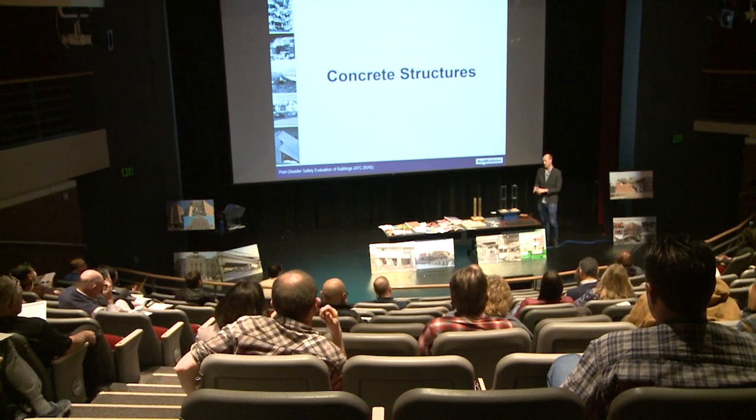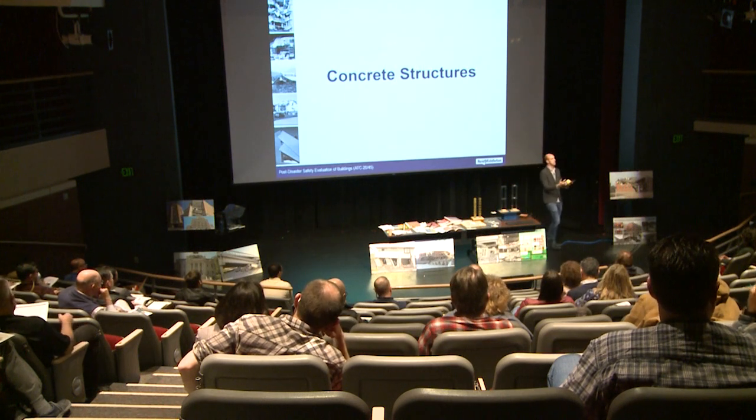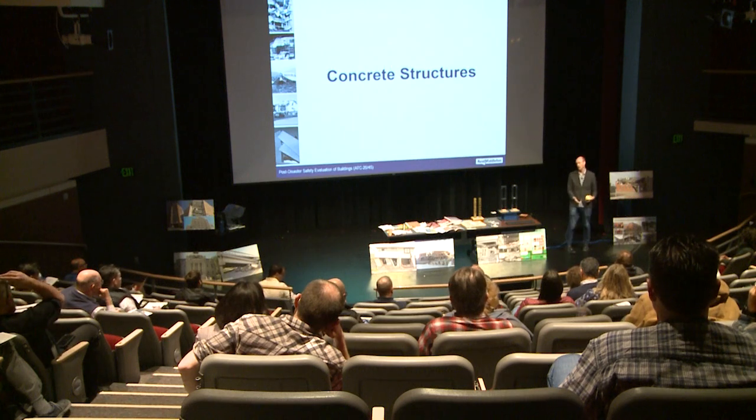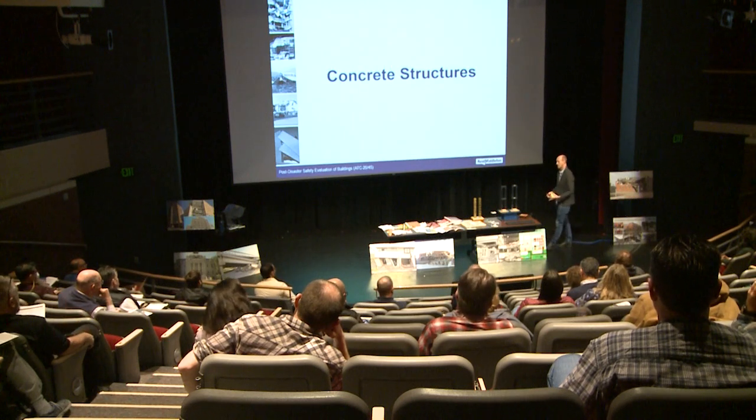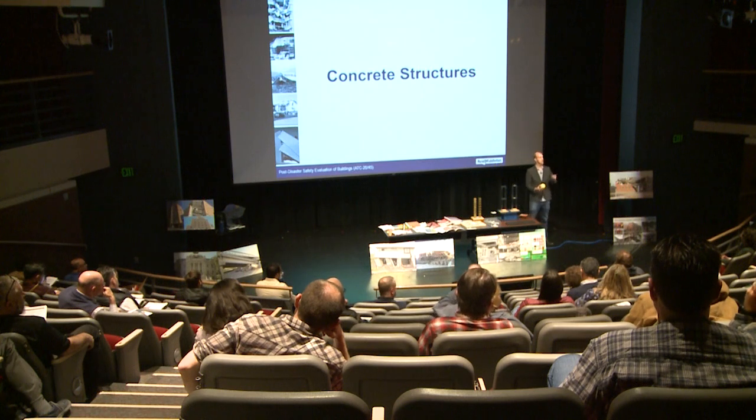Rami showed all these vectors representing the equivalent lateral forces from each floor of the building, and it's all accumulating. So the wall here is taking this weight laterally. This wall, or these walls, are taking those, and it's additive. So all things being equal, it's getting more and more demand, more and more stress. So generally speaking, when you do a post-earthquake assessment of a building, the bottom is probably a good starting point when you look at where the damage to the structure is.